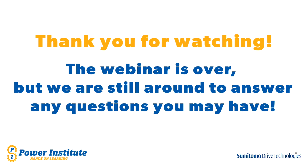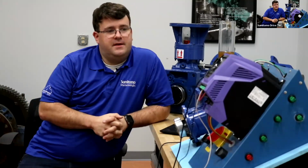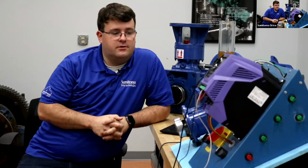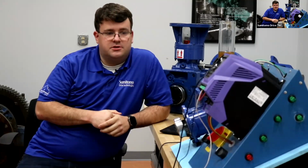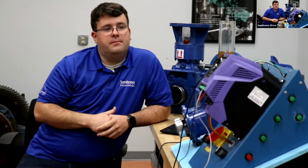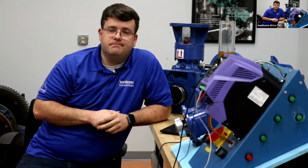We did have a question come through. Have these types of drives been used for CNC machine spindles? CNC spindles, I think we'll have to look into that. There's no reason they can't. It all depends on the motor they're controlling. Those types of applications are normally much higher speeds than what we're running right now, which is about 1800 RPM. But there are some brushless DC motors and things like that, absolutely.